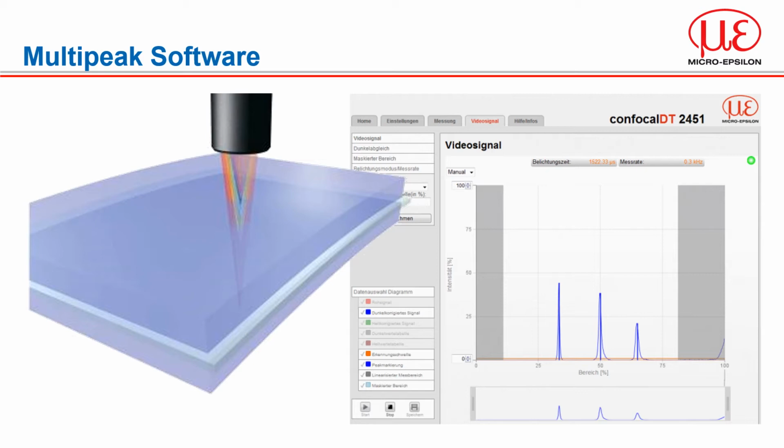To accurately determine the thickness of each layer, the controller retrieves the refractive index for each layer from the material database. Each refractive index is corrected depending on the wavelength with the 3 refractive values used for thickness calibration at the beginning, the middle and the end of the layer.